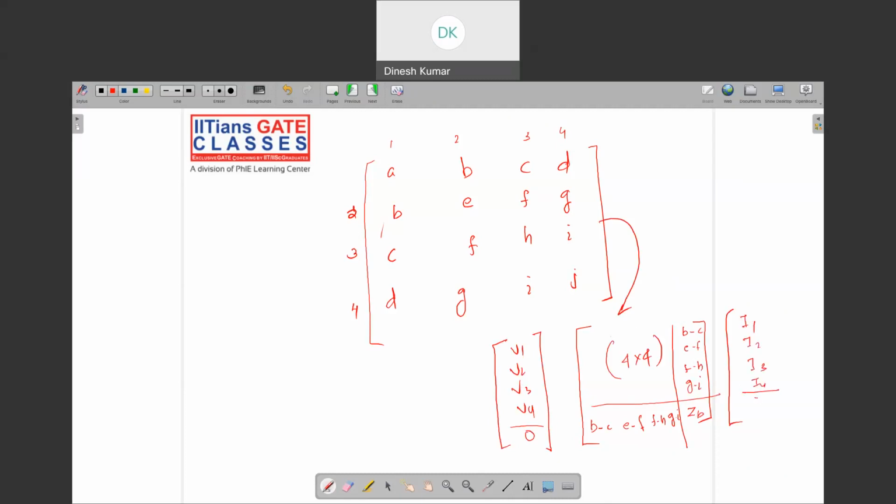Now the new one, that is IP. Okay. Now we can use Kron's reduction because this is 0, right? So we can represent IP as a function of all this, and we can make a 4x4 matrix. Right. So that will be the exact Z bus for this particular case. Okay. So this way we can actually build the Z-bus. This is something known as the Z-bus building algorithm, right? So we can use this algorithm for making the Z-bus from scratch, actually, if you like.